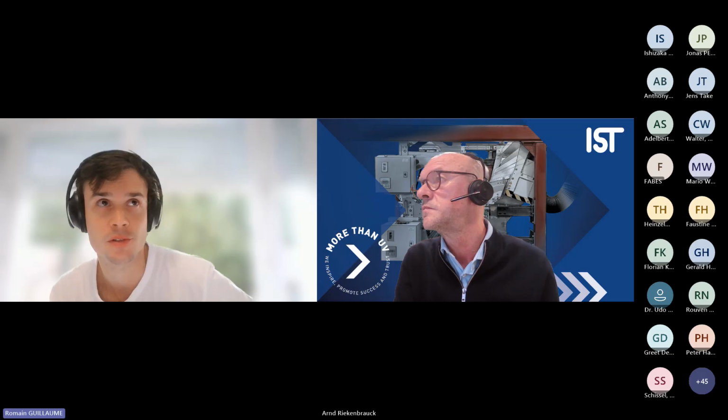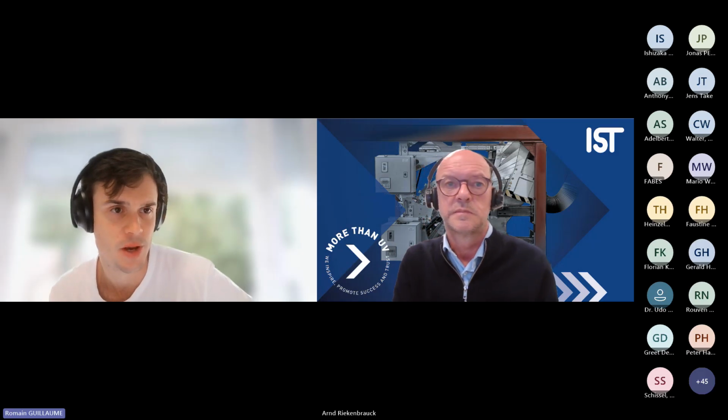Okay, is there still an open question? We have another question from Sonny Liu. What is the lifetime of the FREEcure lamp, and does it have a similar power supply as other mercury lamps? About the lifetime, we speak about a lifetime equivalent to our standard mercury lamp, which is about 3,000 to 3,500 hours. It will depend mainly on the application. But the lifetime, as Arne said, is basically the same. Regarding the power supply, no, it is slightly different because it's one of the innovations in the FREEcure technology, which allows us to improve the irradiation in the UVC spectrum. So the power supply is not exactly the same as for a classic mercury lamp.